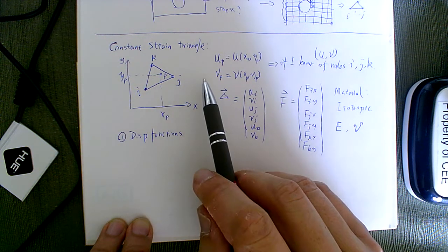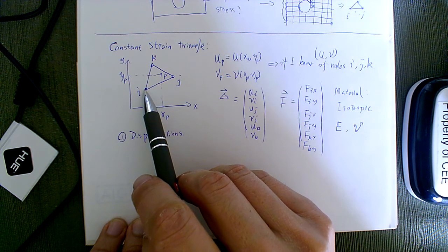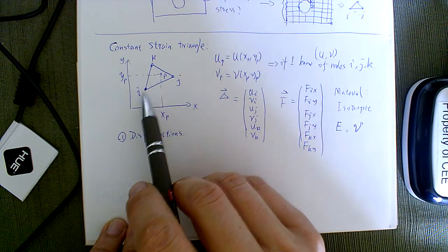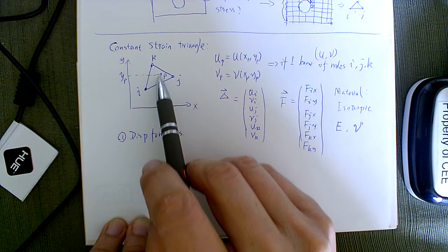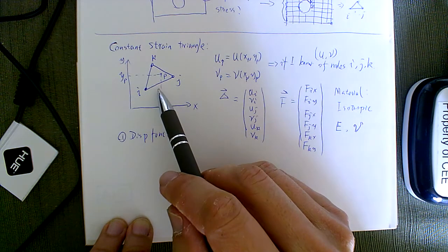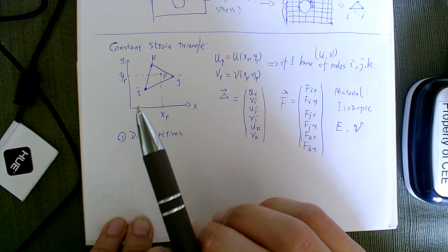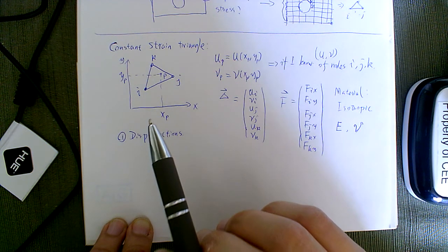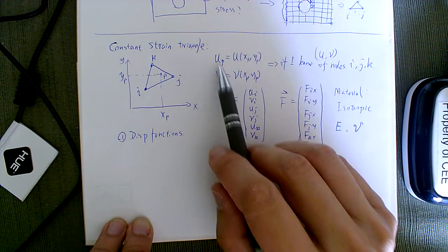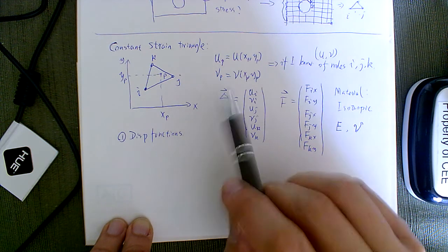It could actually happen, I'm not saying that it could not. Say I don't move too much, but K moves a huge amount, J moves a huge amount, there might actually be some rotation on P. Then P could actually go a little bit closer to I. But those are in the realm of large deformation mechanics. In the theory of infinitesimal strain, if the movement is that large, it actually won't work. Then there might be some correlation between those two, but for our case, it's small displacement, so it should be decoupled.